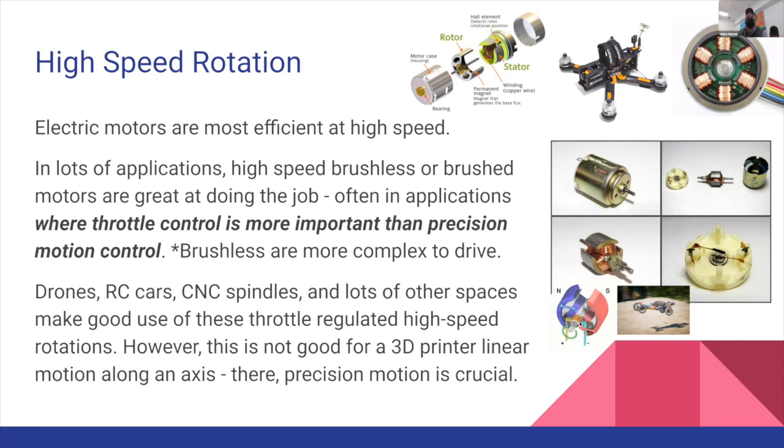That's the actual mechanism. If you ever really feel like nerding out, those $1, $2 fans that you buy on a hot day in a theme park, that you just hold, they run on 2 batteries and you blow yourself in the face with a tiny sad fan. Those things are really fun to take apart. The motors look just like this. They must cost 50 cents to make. And they come apart fairly easily. You can see the permanent magnets in here. You can see the coiled magnets in here, the commutator and the brushes. And all of these are laid out really nicely and cleanly. There's plenty of things to look at with these. There's lots and lots to consider.